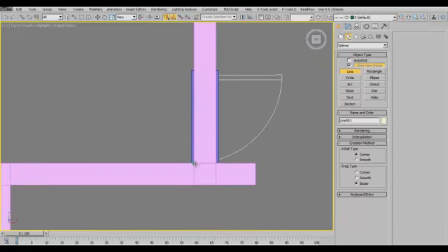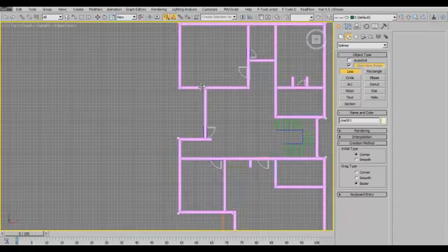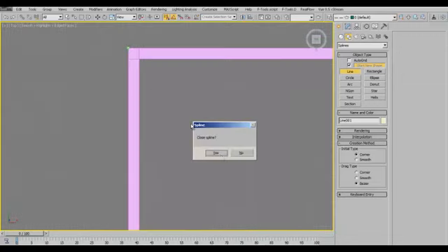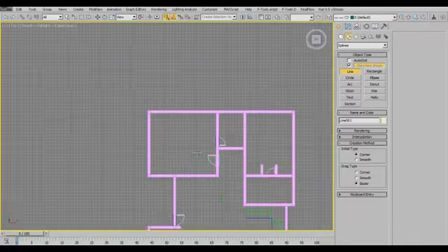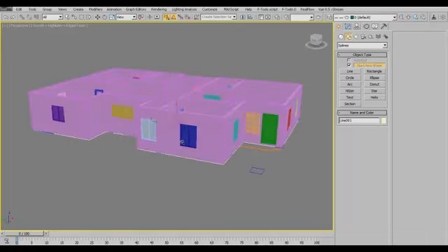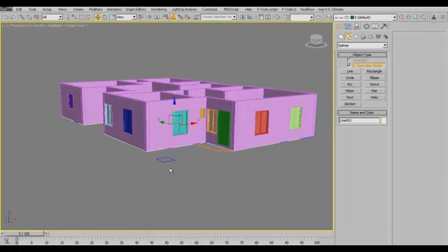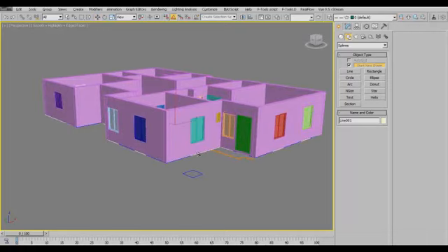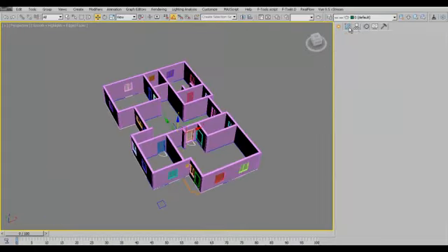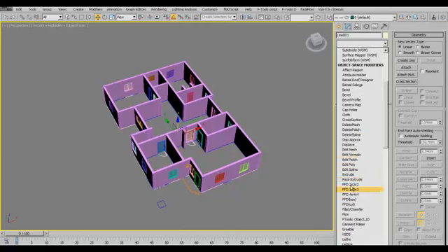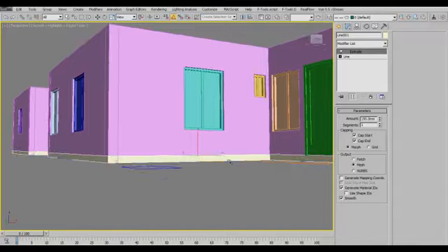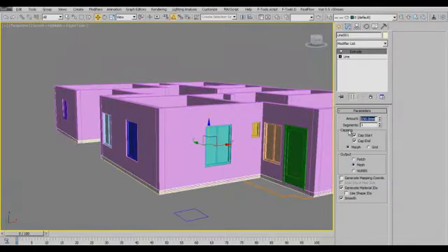To get this to snap here, then this to snap here, then we can accept and close our spline. Okay, now we have that, and no matter what, it will create it on the 0 plane of the z-axis. So this is what we want. Then we would add an extrude modifier just to give it a thickness, which is the 150.